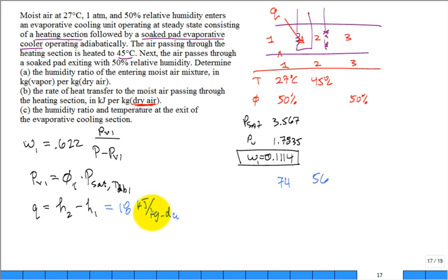Somebody says the book said it's per kilogram of the mixture. I want to make an adjustment to that. Well, first of all, we're fooling ourselves if we're going to use a psychrometric chart. You're not getting 3 significant figures. Get the computer program if you want it that accurate. But it's not that hard to do. So how do you make that adjustment? You say the mass of the mixture is equal to the mass of the dry air plus the mass of the vapor. True?